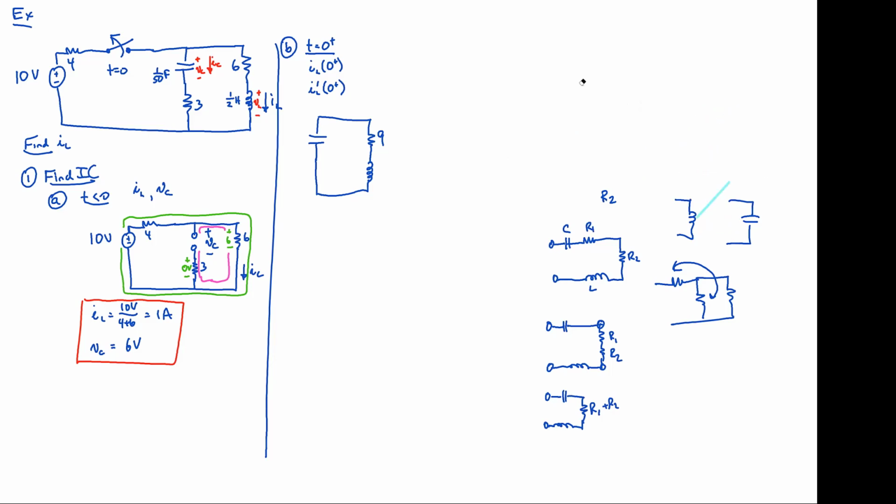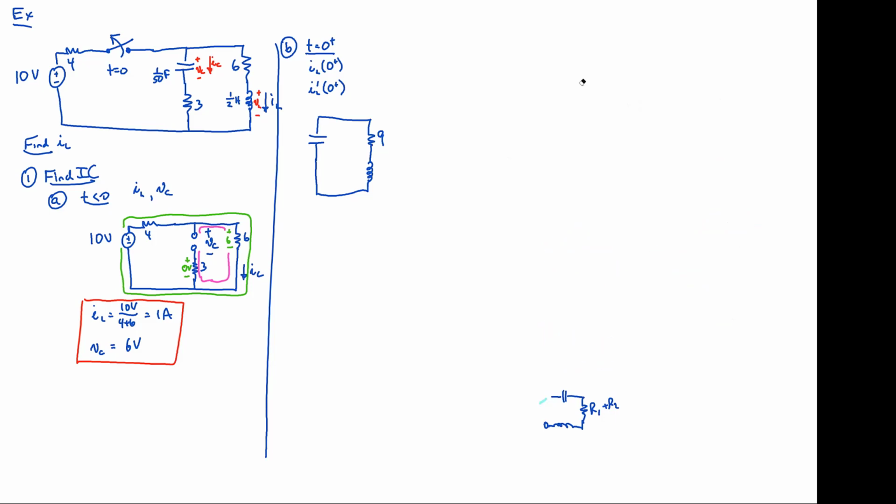So I don't like the word ignoring, because when we start saying when can we ignore things, it starts to sound sort of like magic rules. You know what I mean? And I know I sometimes use that too in its poor form. What we're doing is simplifying. If we've got this 3 ohm resistor, and if for some reason we know what the voltage is across it, let's replace it with a voltage source.